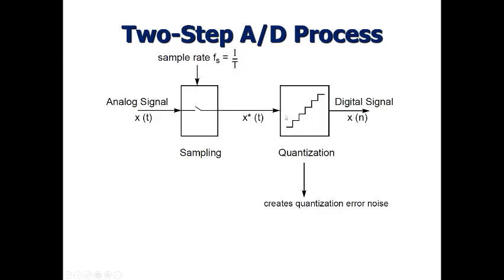That being a quantization process means there's going to be some error, some difference between the signal I bring in and how I'm representing it with a digital signal. And there's some range of input voltages that all result in the same digital output. So if my original signal was closer to this level, well, I've still got a little bit of error between the one I put out and what I actually have.